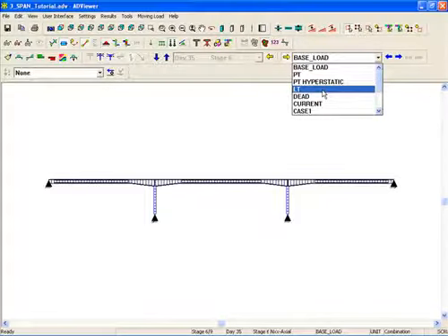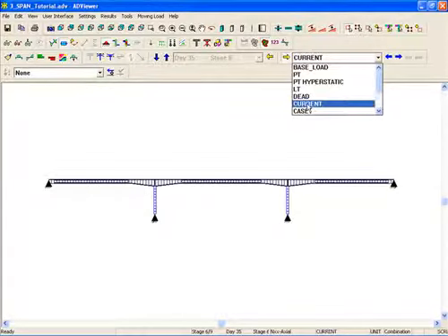LT represents the long-term. Dead represents dead load minus the post-tensioning and also long-term effects. Current includes the base load plus the PT and long-term. It would also represent the last day in the sequencing in the pre-construction phase.